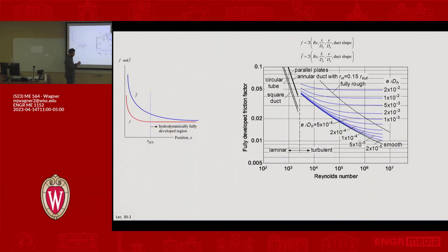It just needs to know the difference between my wall and just a few lengths beyond the viscous sublayer. So things that are important to turbulent flow are things right near the surface. And what's right near the surface? Well, roughness is right near the surface. So here, geometry. Here, no geometry, doesn't care. Roughness is what's important. Okay? So maybe just a new way of looking at that if you've seen it before.